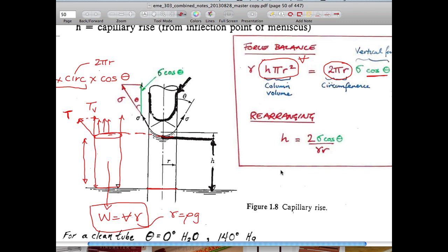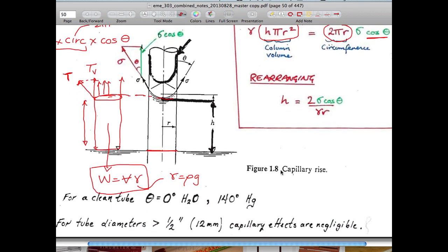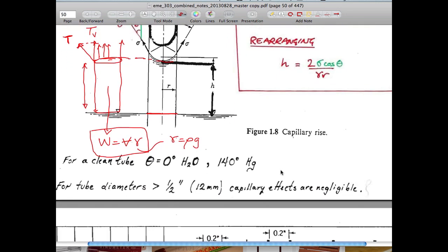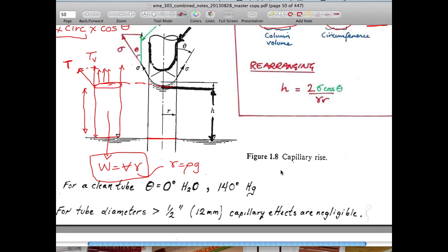So that's one thing, to be able to calculate the height rise in a tube, and it has, as I say, ramifications for flow in porous media where you want to displace oil by a different fluid, say water. They don't mix, they're immiscible with each other, and therefore you get surface tension occurring at the interface between those two fluids. They happen in that case to be two liquids, but the same principles apply.